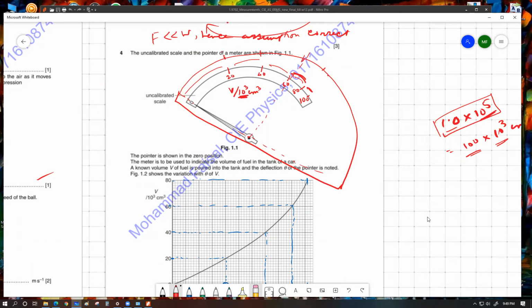the right side, you're just comfortable that there is enough fuel in the tank and you just can drive your car. But as the fuel tank slowly approaches zero, you have a repeated and short interval look at the fuel gauge to observe whether you are actually reaching up to the exact zero value. So the reason it is beneficial to have a non-uniform scale like that, when the fuel tank is quite full, it shows a small deviation because at that point the information is really not that important. But as the fuel starts to empty down within the tank, we have a much bigger visualization that how much fuel is left.